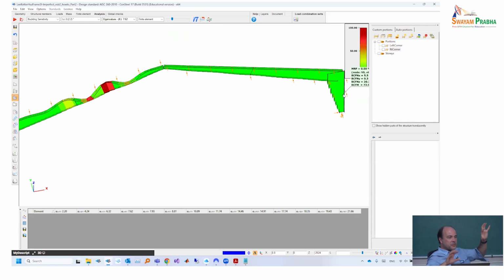Okay, so it works very nicely for those which are definitely separated modes. So it's very nicely separating the well-separated modes. And if a buckling mode seems to be relevant not only for the one where the maximum value is given, but also to the neighbors, as a safe side decision, we also assign this mode to the neighbors. It might not be the most relevant, but there is a certain chance. And to be always on the safe side, we do the assignment.